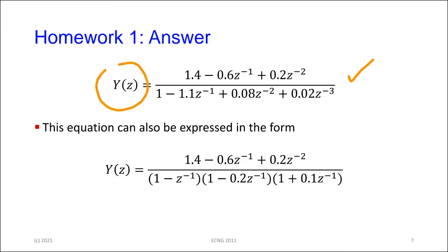Now, this is the system response to our unit step, right? So there's not a transfer function here. We've substituted for X(z) inside of here. Once I do that, I can start to factorize both the numerator and denominator like we would have done in the continuous time domain. So I could find the factors of this, and I can find the factors of that. Usually, if I'm asking you to do something like a third order, I will give you at least one of the answers.